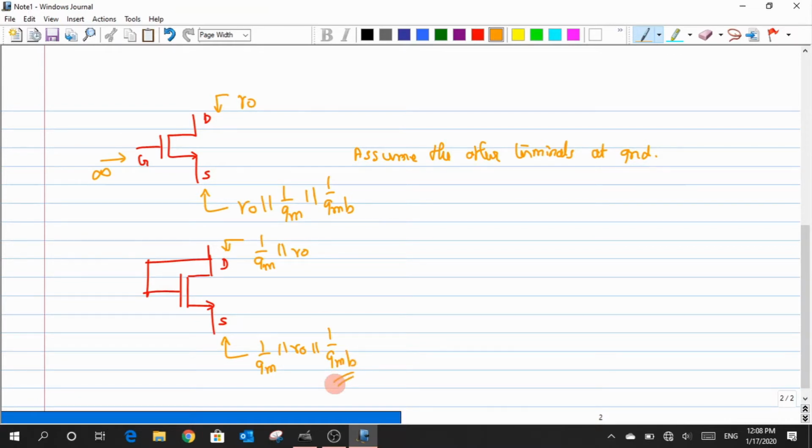Now, we were also looking at one more circuit, but I don't know whether you can recollect because I did it in a hurry. What about the impedance that we look at through the drain? What happens to this resistance Rs? One of the major things to keep in mind is that the resistance would magnify. By what amount? It depends on the intrinsic gain of this transistor. If we build that in, we can then add up the extra terms. Is that clear?